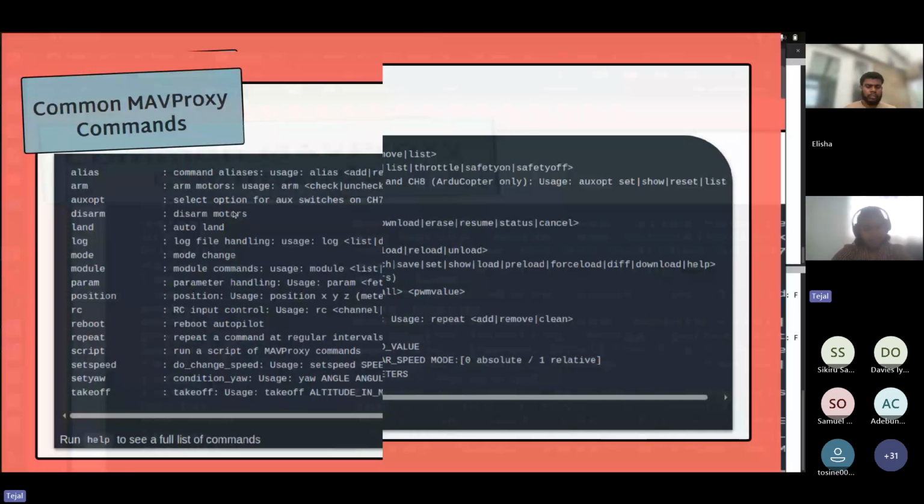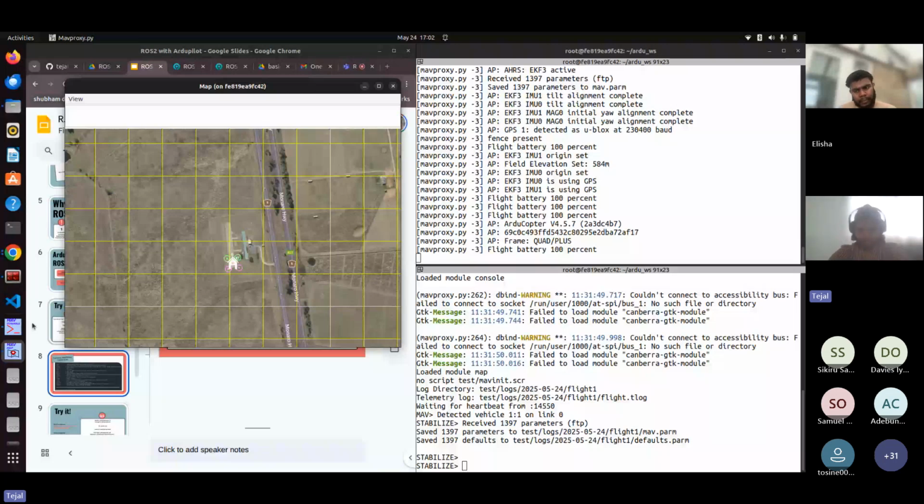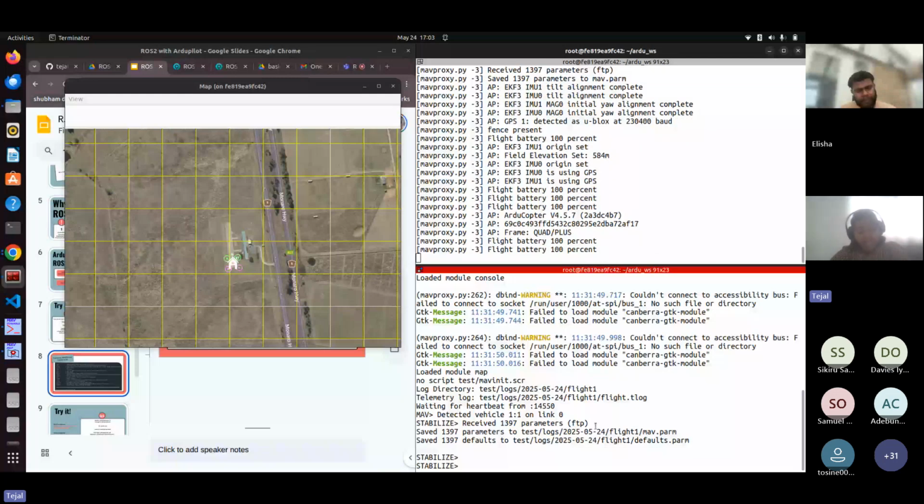In ArduPilot, to give you a very brief overview of the modes that we have, there is something called stabilize, in which the pilot has full control over the altitude, position in X, position in Y, and attitude of roll, pitch, yaw, everything. There are other modes like loiter. In loiter, the pilot is still commanding, but doesn't have control over attitude, only the position of the drone.